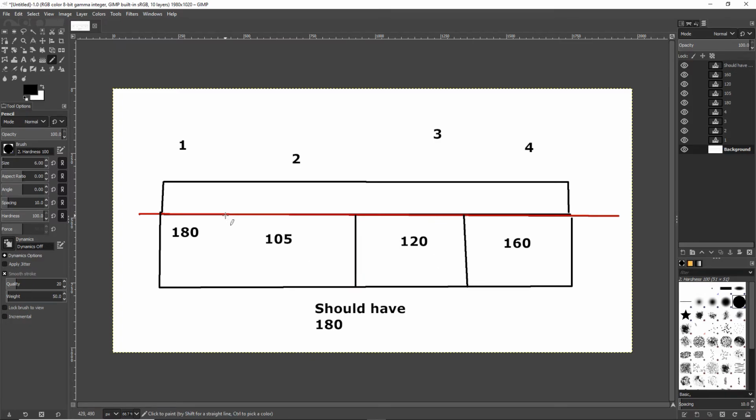So, really, what has probably happened is this engine has overheated, and aluminum does not like to get hot. What I'm suspecting is that across these 4 cylinders, this one looks great, that one looks great. It's probably not a mechanical failure in the cylinder. Probably this head got warped and is beginning to lift. Now, I'm drawing it in a very over the top way. When you look at it, it obviously is going to be a giant curve like this, but it's probably warped across these 2 cylinders here. And that compression, instead of going where it's supposed to go, is probably bleeding into the neighboring cylinder.